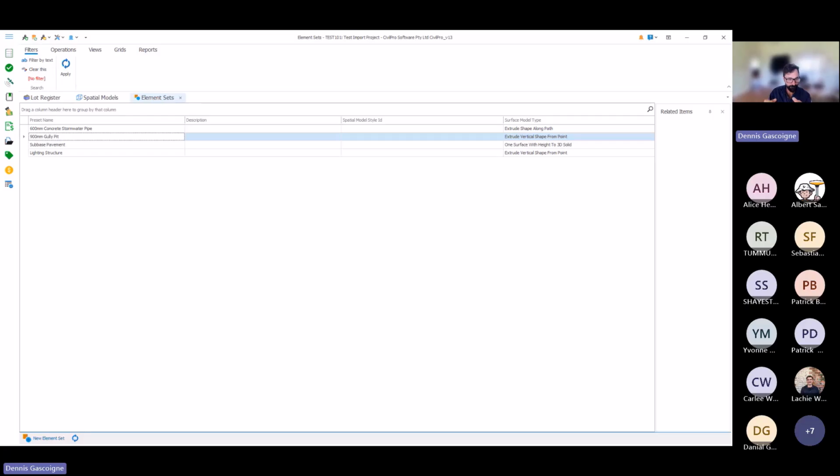That's obviously the first one, when you create from an existing model item, where we're basically pilfering the definition from an existing model, amending it with all the conformance data and outputting it. The second one is the surface extrusion, where we just cookie cut through a surface. The third one is when we extrude along a polyline with a shape. And the fourth one is when we just drop a shape around a point. So yeah, that's the intent.